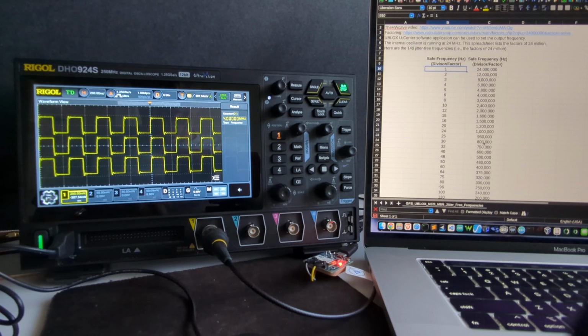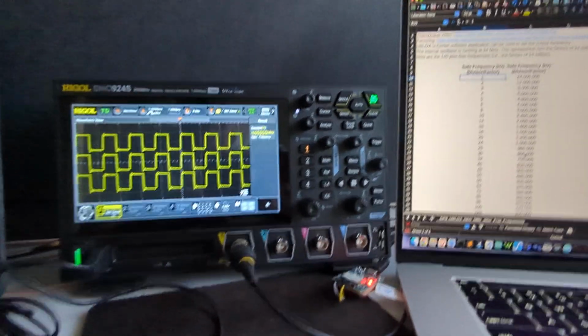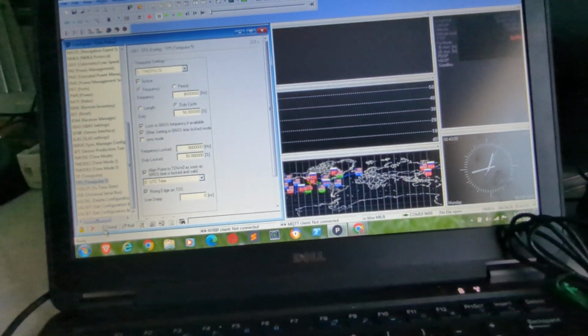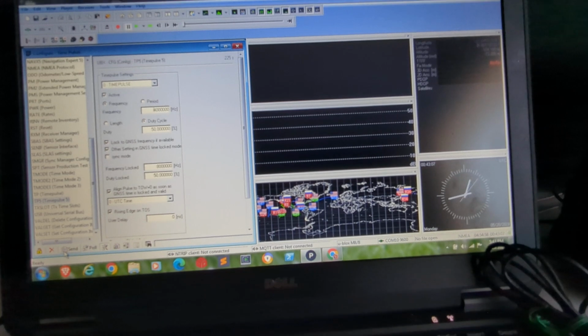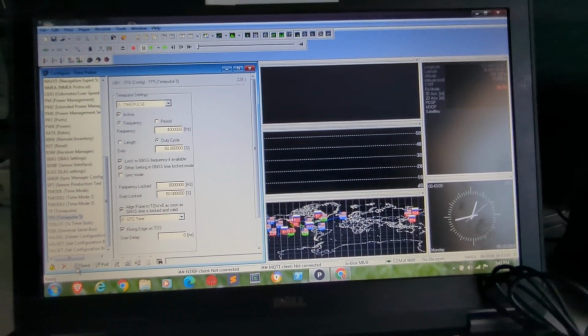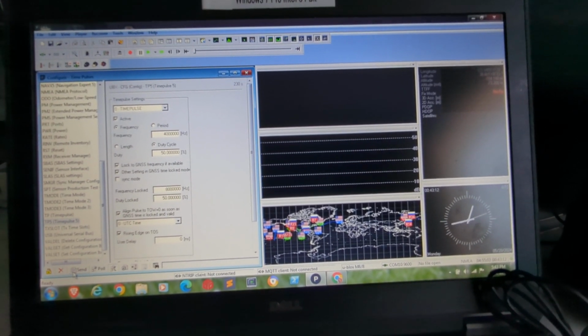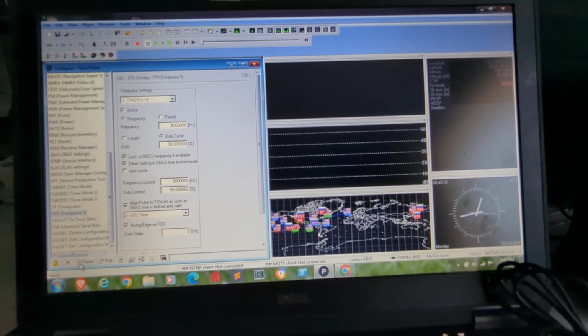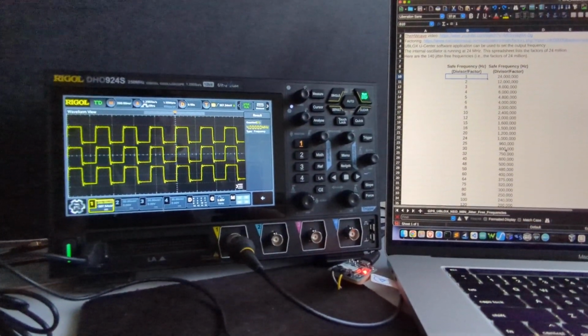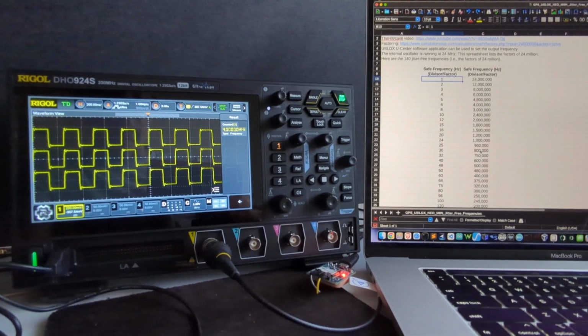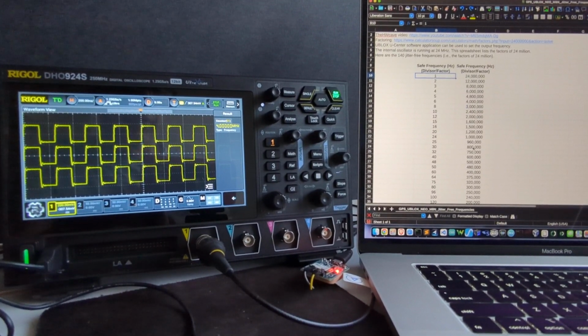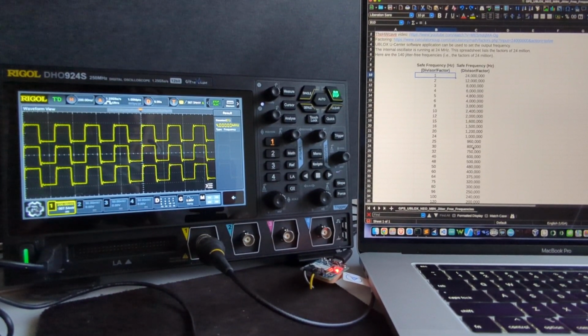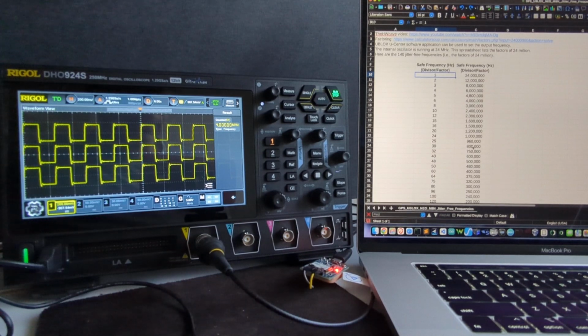What I'm going to be doing is using the U-Center software, which is freely downloadable from UBLOX, and it's the software you use to configure the frequency that you want out of that PPS pin. I won't go into how you do all that, but that other video that I pointed you to has all those details. There's others online that have shown how to do that as well.